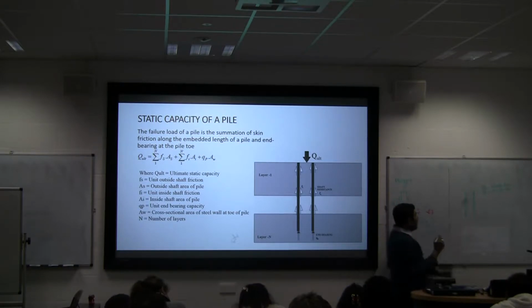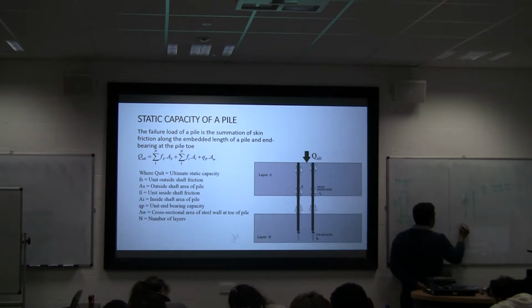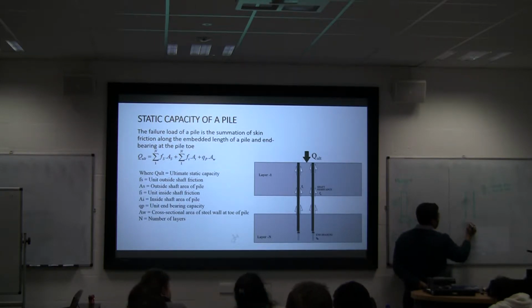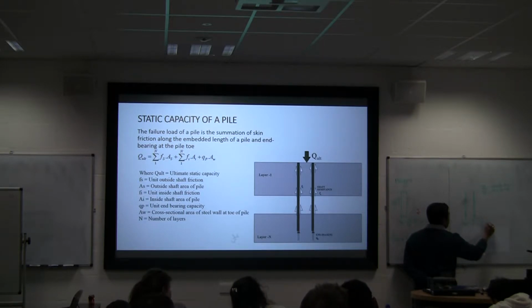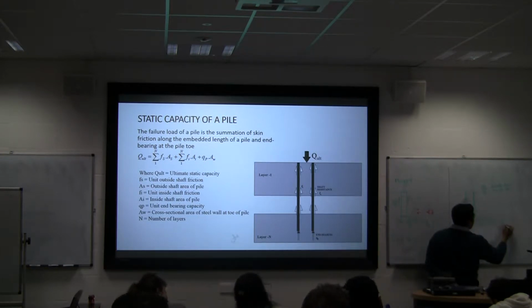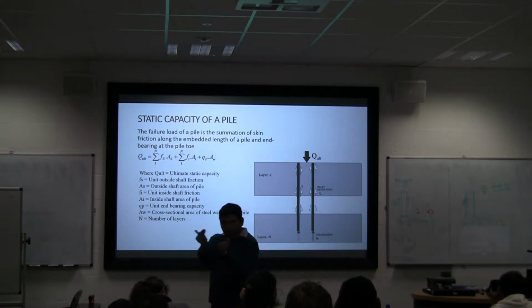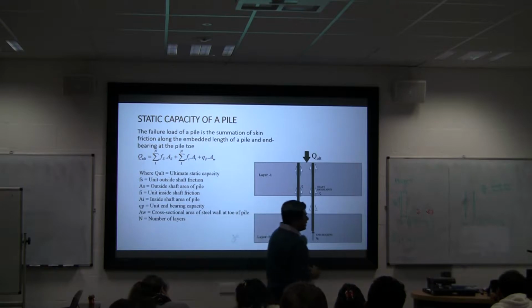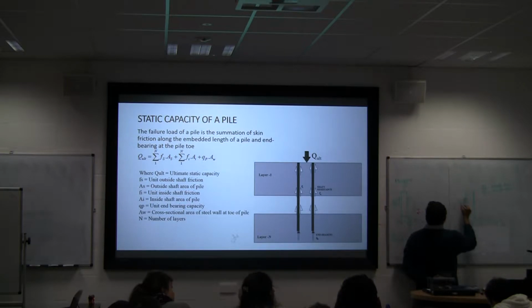Now here the end bearing will be only in the annulus part. So therefore here QB would be pi by 4 (DO squared minus DI squared) times qB. Yeah? Only annulus part. But then you have here twice friction, QS also inside as well.